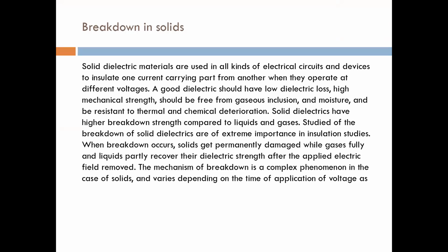We know that solid dielectric materials are used in different electrical circuits to separate or insulate one current carrying part from the other. A good solid dielectric should have low dielectric loss, high mechanical strength, be free from gas inclusions and moisture, and be resistant to thermal and chemical deterioration. These are the good properties of a solid dielectric.